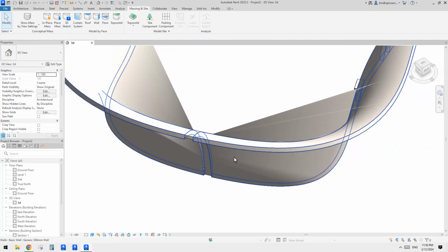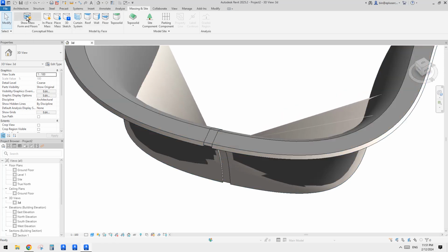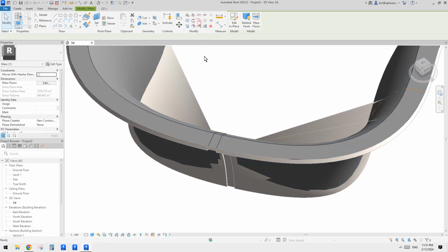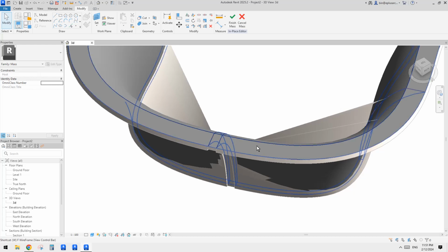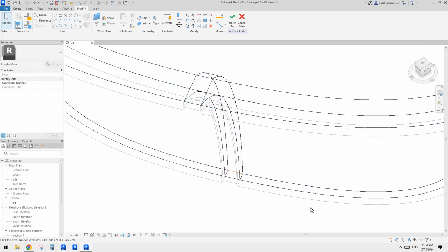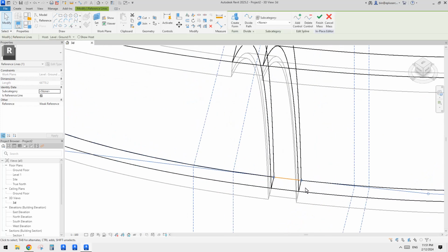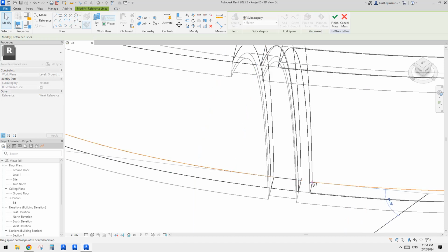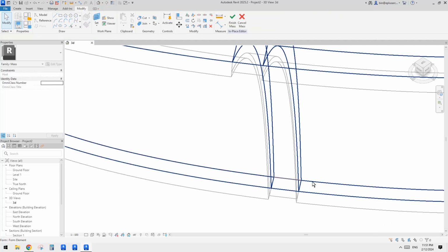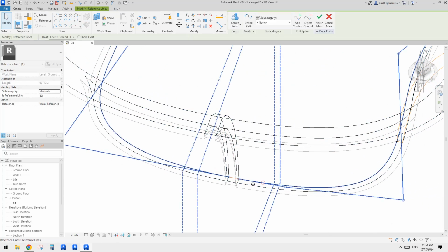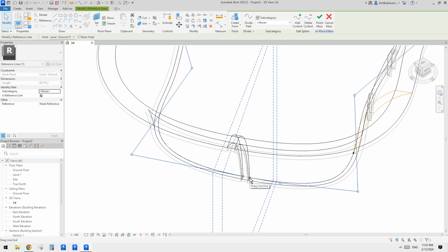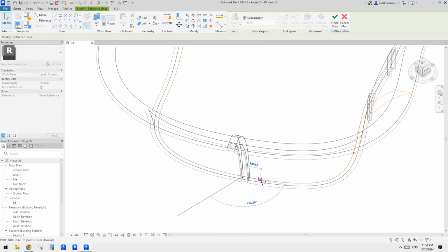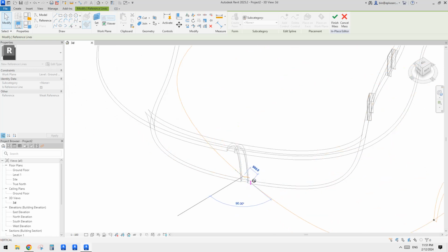Okay, so first we need to bring back the mass, right? So then select this, edit, and go, or type WF, because I try to pick the path here, right? So now we can drag. Remember to use tab to only pick the endpoint. Otherwise, you will change the scale of the whole thing. So let me show you. If I do not tab, and if I directly drag this, it will do this. See, it will scale this thing, scale this path.